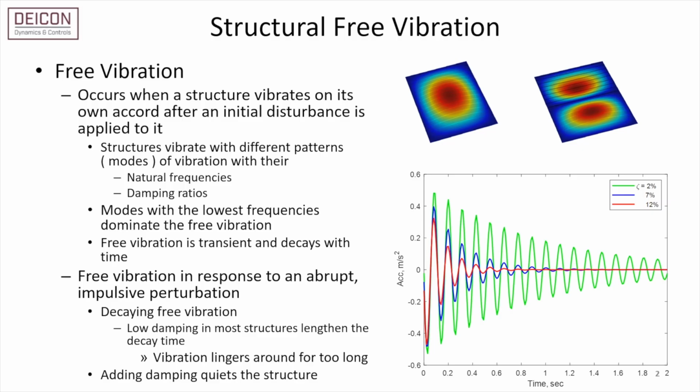Essentially, the vibrations persist for an extended duration, presenting challenges in vibration management. Introducing additional damping facilitates rapid dissipation of vibrational energy, contributing to a quieter and more controlled structure. These three traces show the acceleration of a 1 degree of freedom structure with 3 different levels of damping.